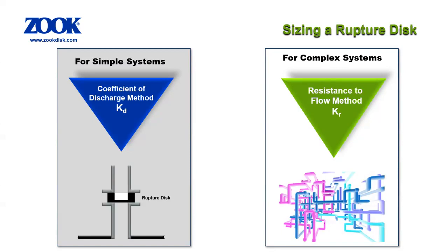Caution should be taken when selecting rupture disk designs based solely on a low Kr, as this can lead to a small diameter relief system with limited options to correct the value if changes in disk or pipework design are required in the future. Vendors can offer useful advice and sizing assistance, but ultimately, the responsibility for sizing lies with the end user. The takeaway here is that right sizing is the goal, which requires collaboration between the user, process engineer, and the disk manufacturer.